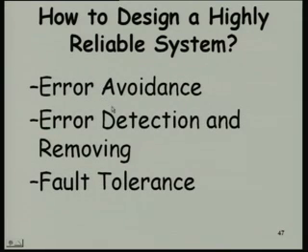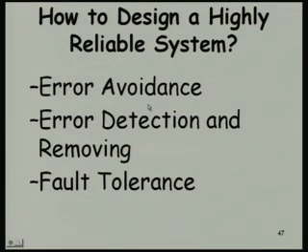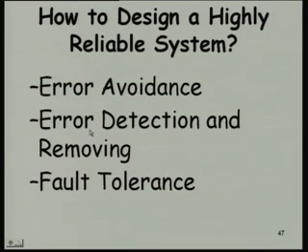One is error avoidance, as he was saying, that we can use some systematic methodology where we reduce the chances of error, we avoid errors. The other is testing, to detect errors and then remove them, test it thoroughly, and still there will be chances of problems, because we can't really test with all exhaustive values. There are too many of them to be able to test in a reasonable time. So, we will have to have fault tolerance features in this kind of safety critical systems.